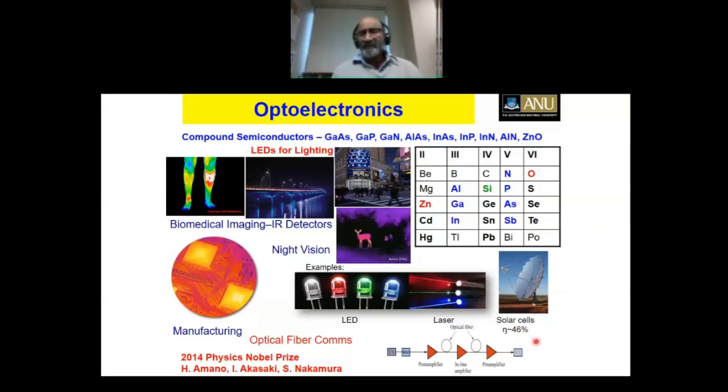But once the 40% efficiency had been exceeded, people started thinking about how can we use it for terrestrial applications. So people have been developing something called concentrated photovoltaic systems, where you've got a light concentrator using parabolic mirrors, and then you really concentrate the light at this focal point. And because the concentrator system cost is so high, you want to have the most efficient solar cells. That's where the 3-5 compound semiconductor solar cells have been explored for this particular application also.